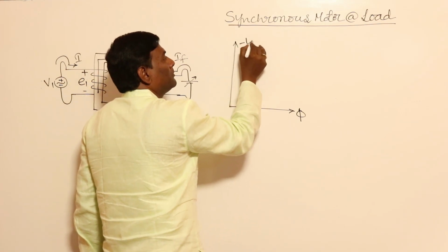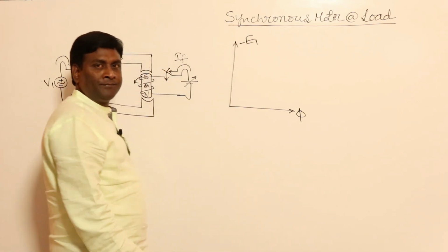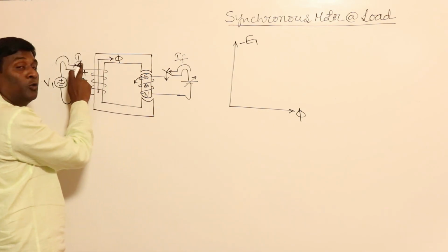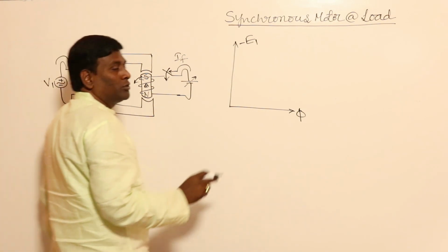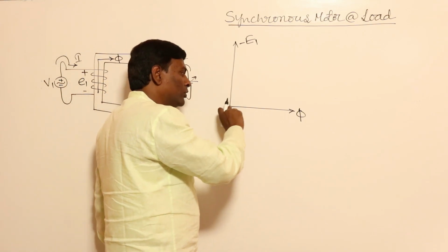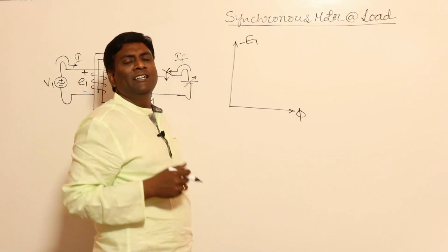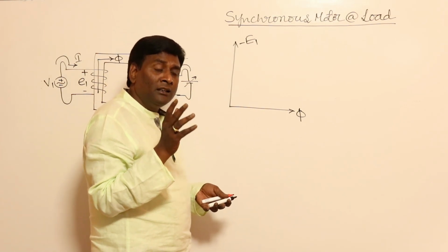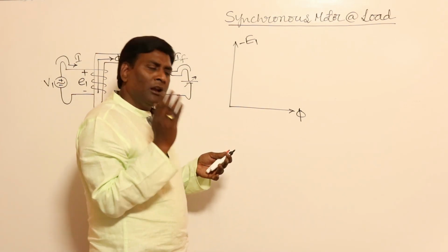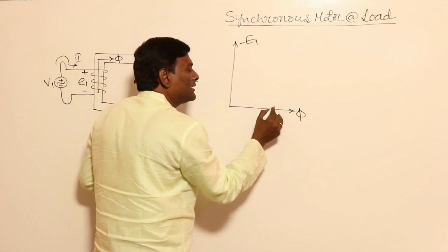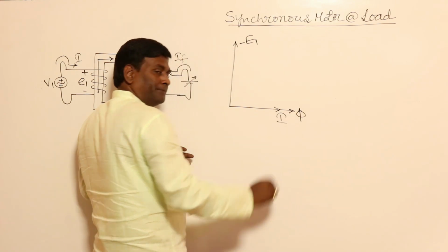So this is going to be minus E1 equal to V1. How is my current going to be, more or not? In the transformer we considered the no load current like this because of hysteresis and eddy current, but that non-linearity need not be bothered now, because that non-linearity and double valued BH loop were already discussed in the transformer. So directly I will consider I here.